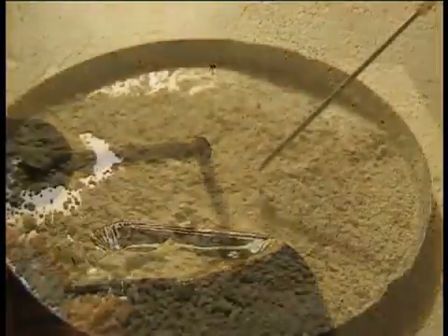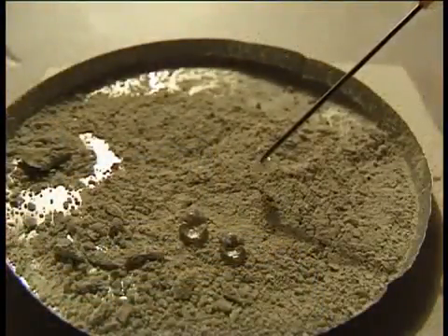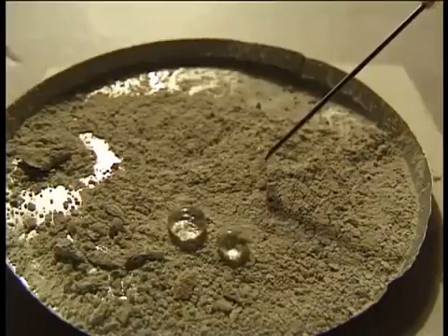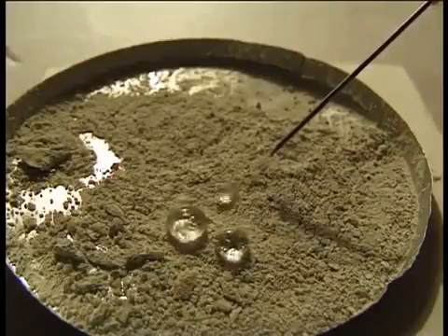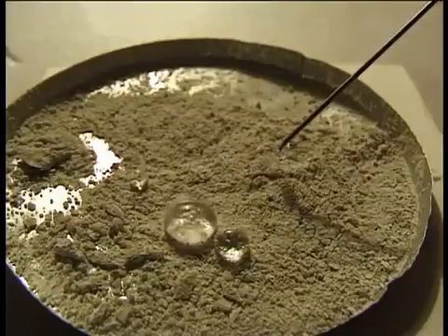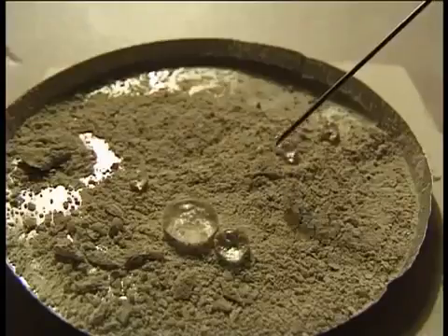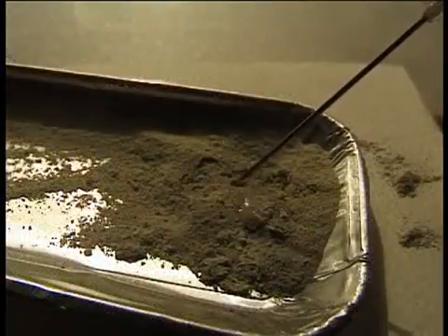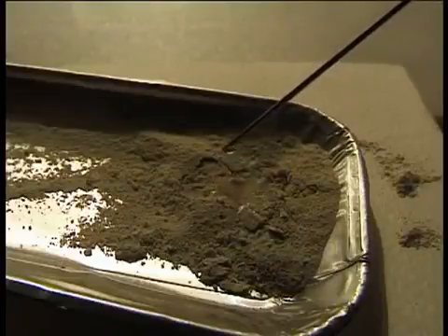A simple test, the Aquapol hydrophobia test, shows the water repellent properties of the restoration plaster one has used. Distilled water which is used for this purpose is purified of salts and minerals and is not absorbed from the plaster. Here is a test with ordinary lime and cement plaster to make the difference clear. As you can see, the difference is enormous.